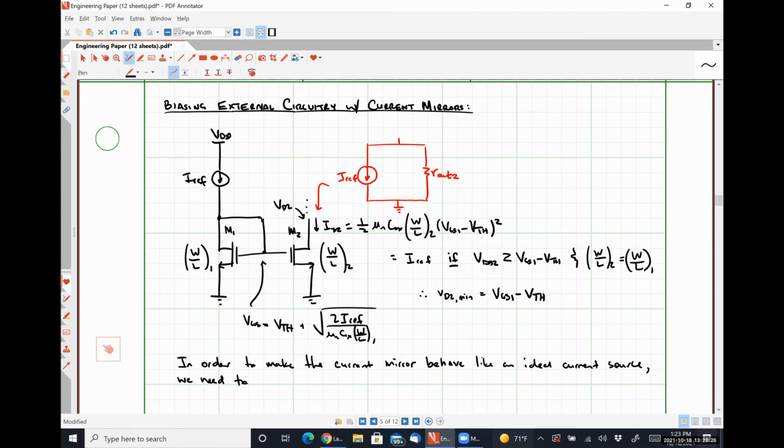All of you have had circuits one, so all of you should know the answer to this question. Exactly right. So the practical current source has some internal resistance, R out 2 in this case. And the ideal current source, well, it has one as well. What's the internal resistance of the ideal current source? Infinity, right? If it were 0, there'd be a short circuit across it, not an open circuit across it, right? So if we want this guy to behave more like an ideal current source, we need to make R out 2 appear larger.